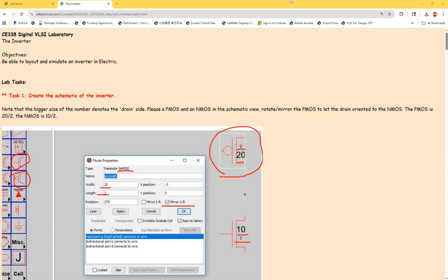But do you know what's the most popular technology node currently on the market? Digital circuits wise, it's actually 28, even though TSMC can do 5 nanometer or 2 nanometer. 5 nanometers was 2 years ago, and now they can do 2. At the minimum length, it's just like several atoms, but the thing is, it's super expensive. If you fabricate a prototype with TSMC at 2 nanometers, it's probably like $5 million. But 28 nanometers is still doable.